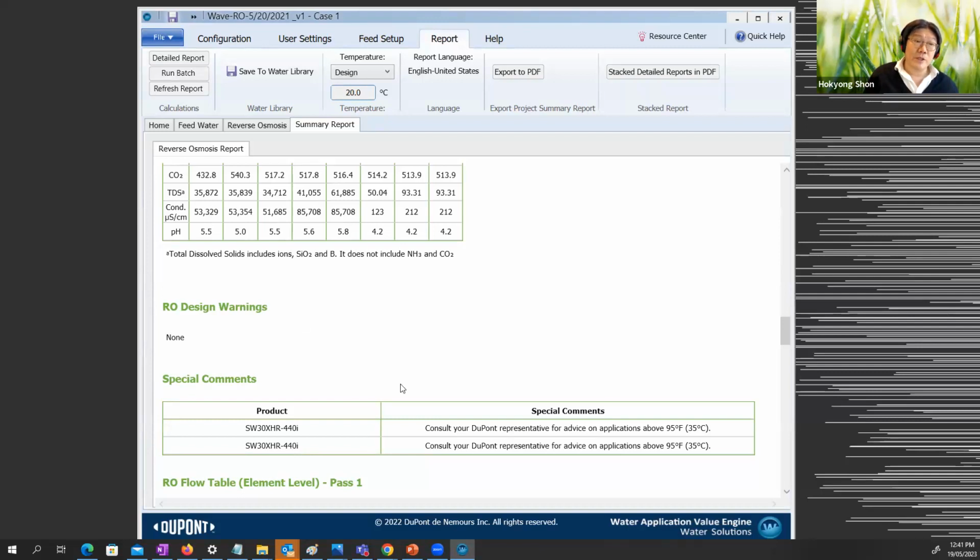So you have to calculate more pressure vessels in your system as stage 1. So Dinesh, what you have done is a little bit less calculation of your pressure vessels and elements. So you need to increase more based on your flow rate, your productivity and the recovery ratio.